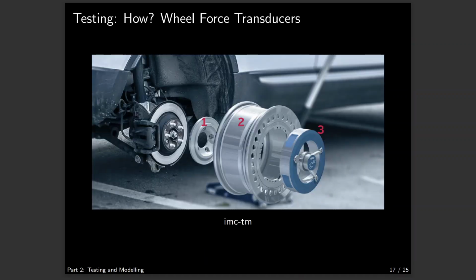Finally, wheel force transducers can be mounted directly onto an existing car. Now, we can test tires with the actual car and road they're going to drive on. While this does pose repeatability and controllability issues, it can be very beneficial if one wants to see how car setup changes can affect the tire. I've heard rumors that this is an extremely expensive testing method, but I wouldn't know exact pricing schedules. In the end, the testing method I recommend is however much you can afford, because if you have real tire data, you are already leagues ahead of several professional motorsport teams.